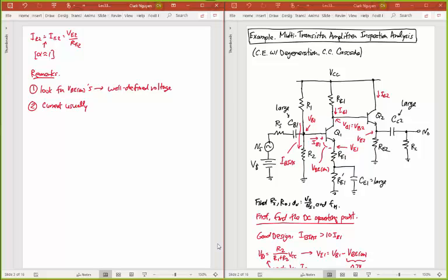So I'm going to write that currents are usually determined by an emitter voltage divided by an emitter resistor value. So I'm going to say it's usually determined by VE over RE. Okay, and then finally I'll repeat what I've already written there, but especially when you're doing design.